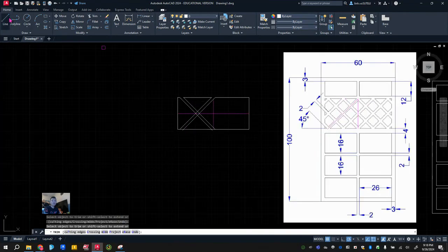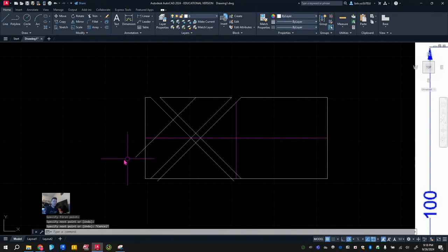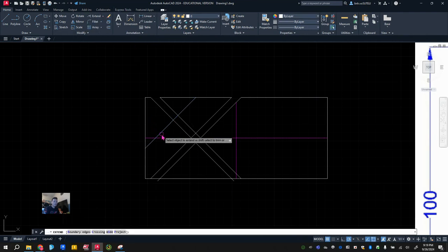So I'm going to go right here and click on that midpoint, the triangle. It's going to go up. Same thing. At this time, I'm going to draw a 135 degree line, which is already there. So I'm just going to hit enter there. And let me click on it and get rid of it and try to do it again. All right, so that does not look like 135. Right there, you can see 125, hit tab. I'm going to do 135. There's my angle.